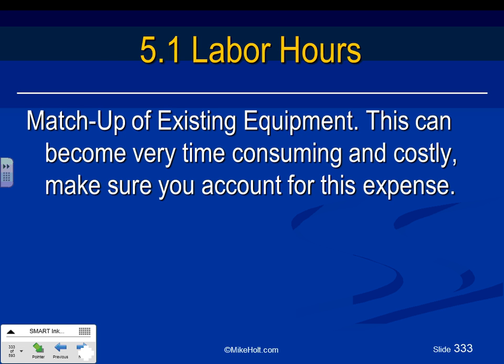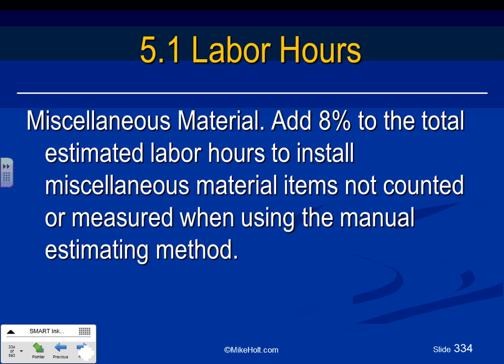Match up of existing equipment. This is interesting. Matching up of existing equipment. With being, guys, in projects as an engineer, you walk in and they have a GE switchgear, and you will match up their GE switchgear by adding to it. So you get it. Now you're getting into more time to go coordinate. How are you going to match up to this lineup of switchgear? If you have to match existing equipment, then you might be married to a certain manufacturer. You might have to do a lot of coordination. So that will add to your labor.